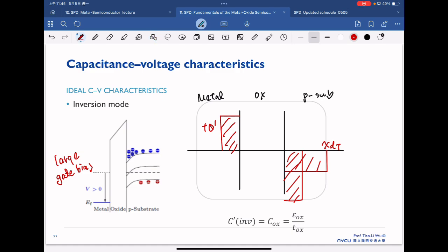So again, we have this dQ, where we have the dQ plus here, and this additional AC induced dQ will cause the additional inversion charge in the channel, and therefore this dQ plus will exist in the channel rather than at the end of the depletion width here.